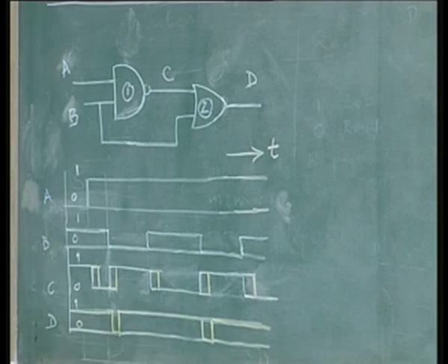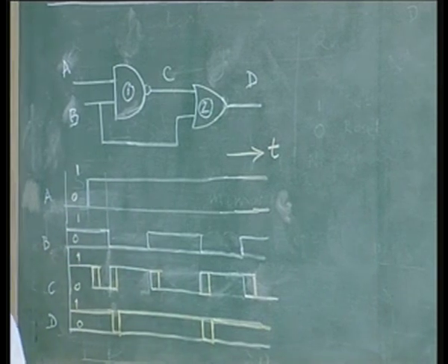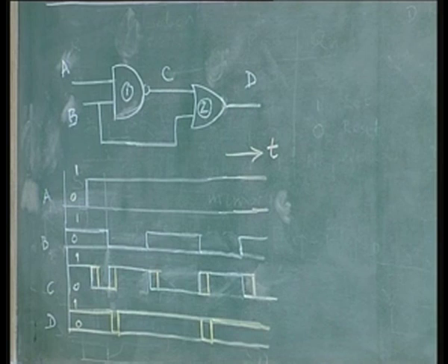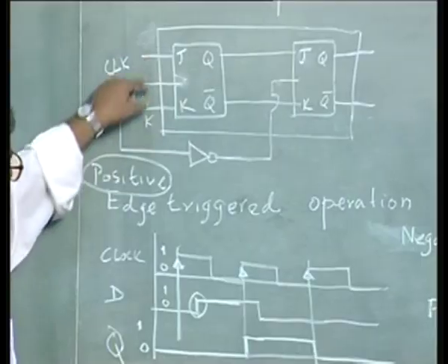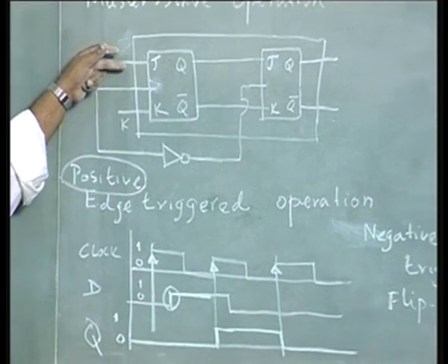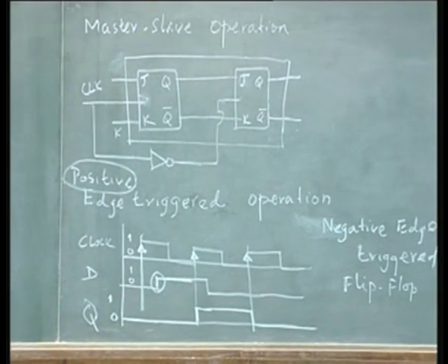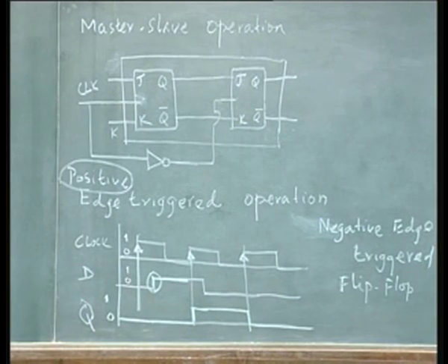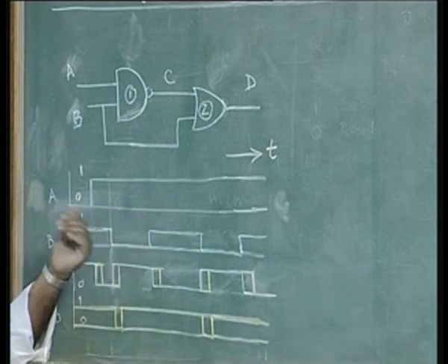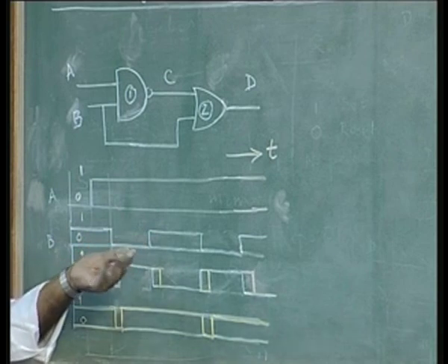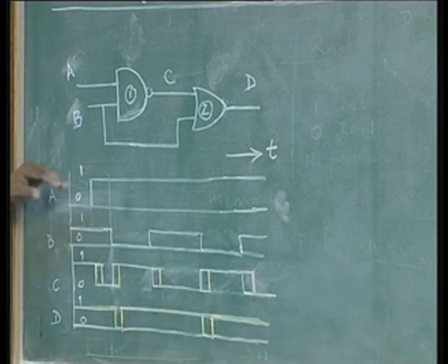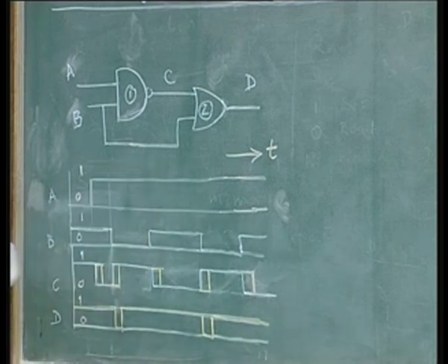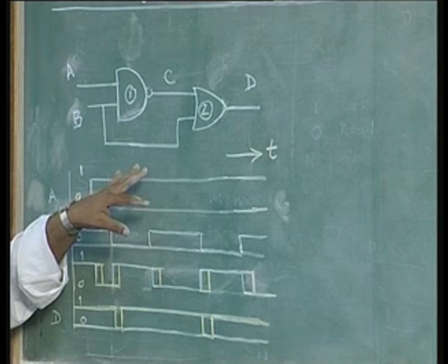We said that the edge of the clock determines the operation. Only during the clock edge any input will be recognized. It is easy to say, but how do you implement it? Because when you are going to have a flip flop of JK type here, we have inputs occurring and the clock occurring, and you cannot suddenly remove one of them and say it is only for a short duration. So, the actual way in which it is done is to put an extra circuitry at the input of each of these flip flops. Each flip flop input, that means if it is a JK flip flop, 2 inputs, for each of these inputs you need to put this extra circuitry. So, there will be an extra circuitry that has to be put at the input of each of these. Let us just understand this circuit. This is one of the possibilities. This is not the only way in which you do the edge triggering.